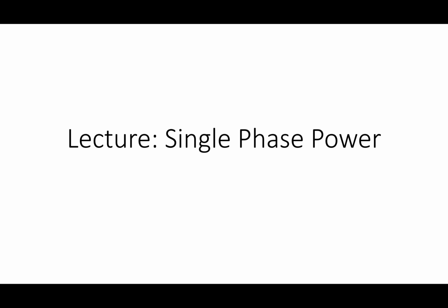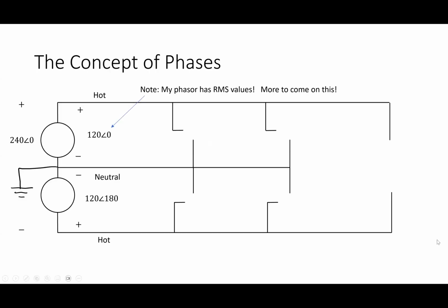All right. So in this building, what do we have? Here we have three phase for sure. Commercially, you always have three phase. Residential, you have single phase. And that single phase is kind of weird. It's actually what we call split phase. All right.